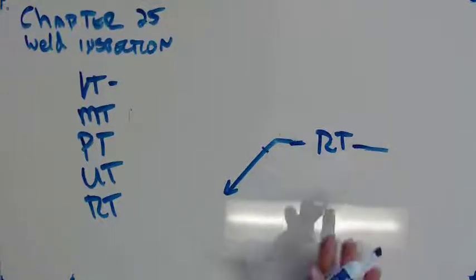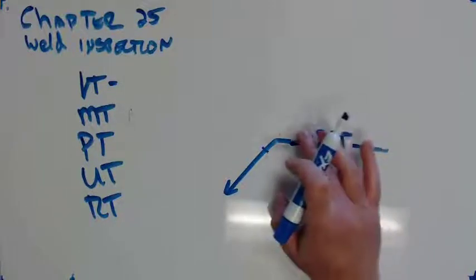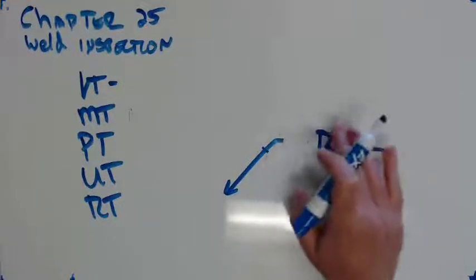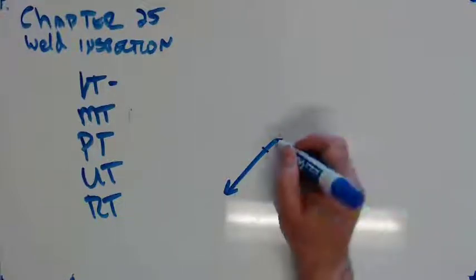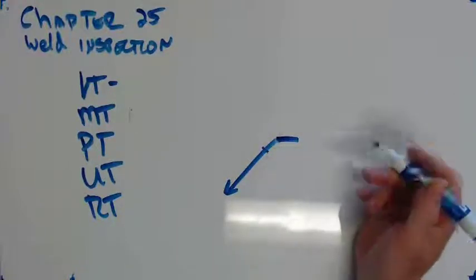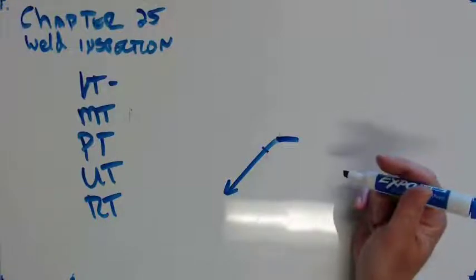Usually, and this is real common, it's not just one thing. There's no reason to do radiographic testing if I'm not going to do visual inspection on it first, or any of them really. There's no reason to bring out the mag guy if I can see flaws with the naked eye.